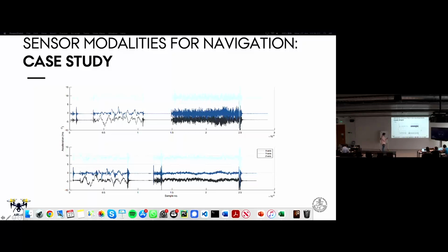I should also mention, this is an accelerometer reading from the drone, from an autopilot implementation called Pixhawk, and this was showing us the vibration on what's called the base link of the robot. So this is what the robot itself was experiencing. Because the base link was quite close to the camera, we figured out that the camera would require some dampening, so the engineering that we did was put rubber dampers on the camera, and it worked very well. You can see now that the noise is reduced, and we could work the SLAM quite effectively. Thankfully that was solved.